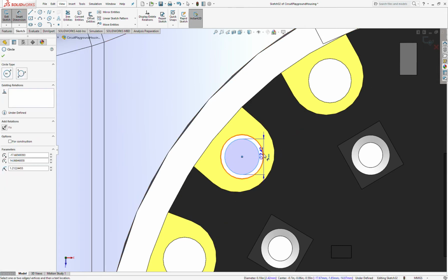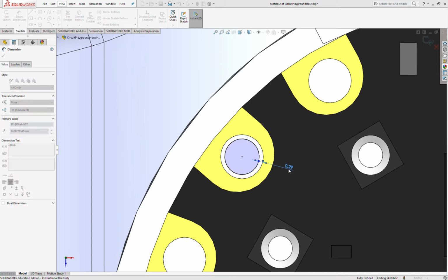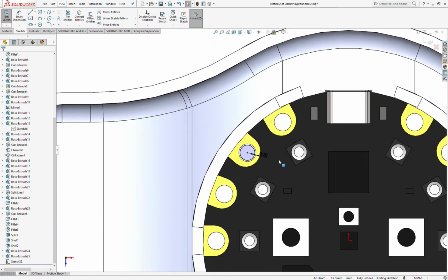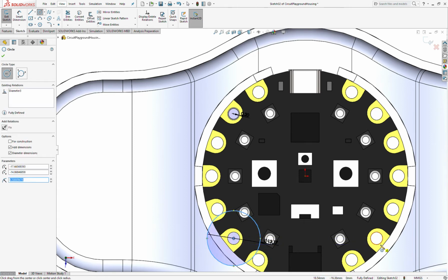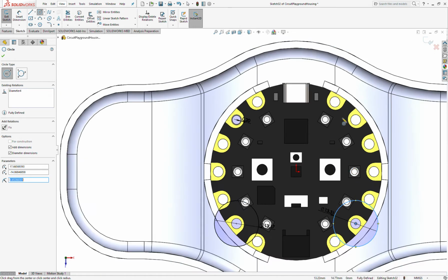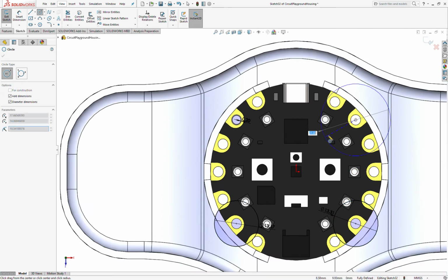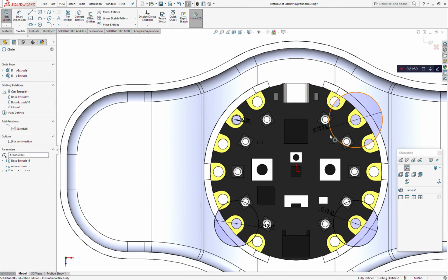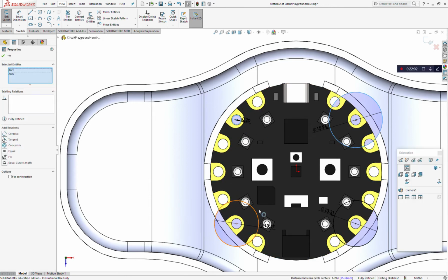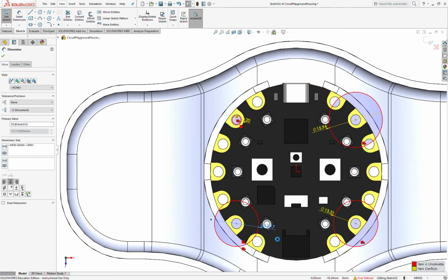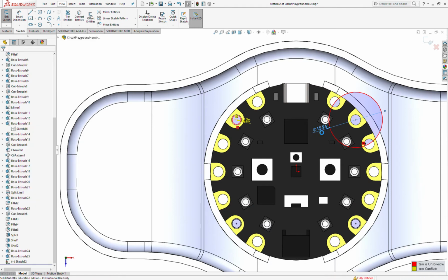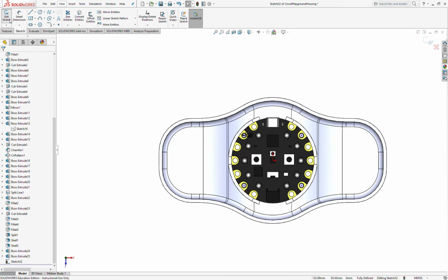We're going to make this 0.2 millimeter offset. And we're going to throw in a couple more of these circles. So, one over here. One over here. And as I'm drawing these, I'm just getting them in, because what I can then do is just relate them all back to that one that's fully defined. But it's going to throw an error because it's putting them in with diameters.